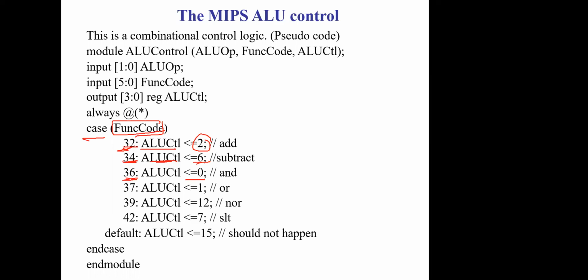And again, you have to define the module, you have to define the inputs and outputs, and then you will have the always block. And of course, with the always block, you have a sensitivity list here. We already explained in the other lectures what is exactly meant by the sensitivity list. Meaning that to which input you should be sensitive.